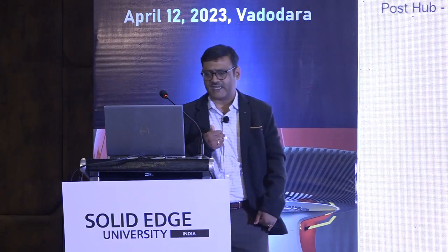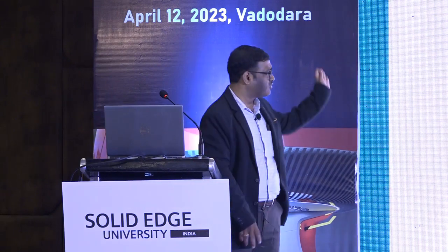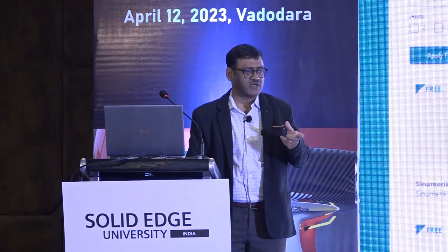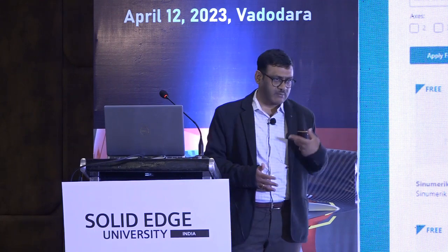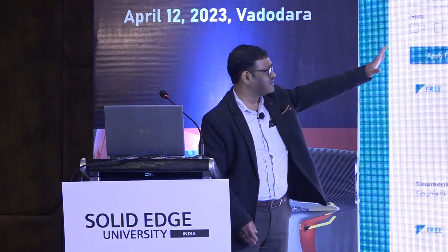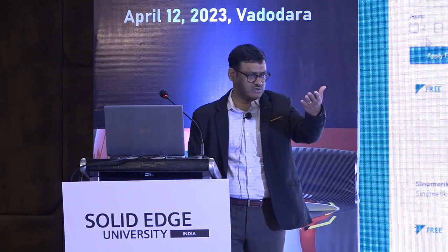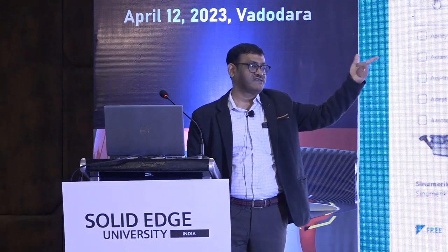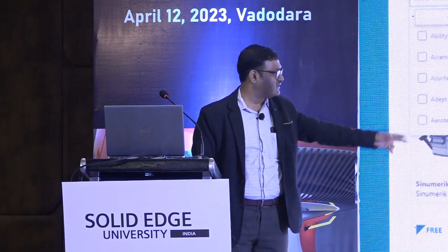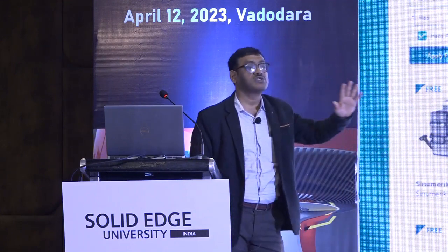If you are under maintenance, you can go to our website and download all the post processors that are available. This is how Post Hub works, because in CAM, unless you convert the toolpath into G-code and M-code, it is not recommended for anybody to use it as it is. Go to the Hub, which is Siemens certified, and search for your machine. Let's say you have a Haas machine or a Jyoti machine. You search by machine manufacturer, controller, or axis, and you get relevant results. Some are free, some are charged a little, but solutions are definitely available.